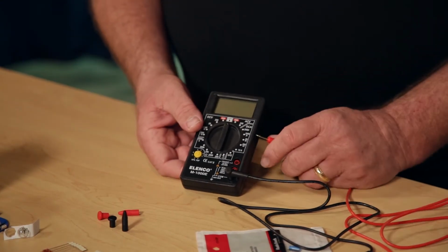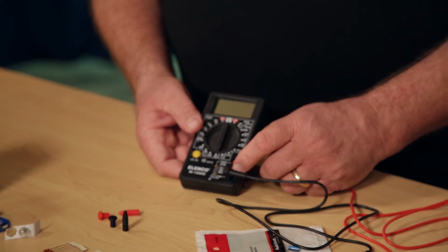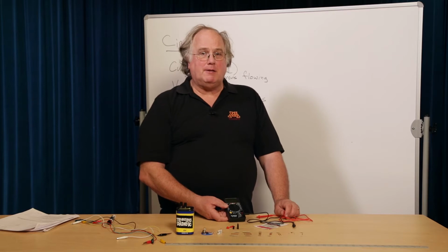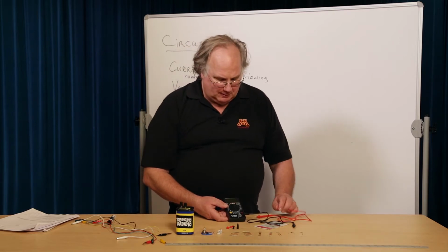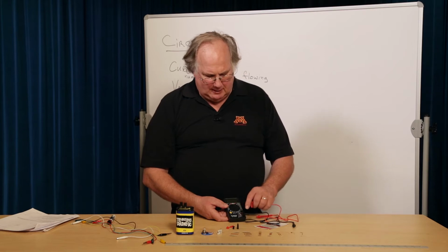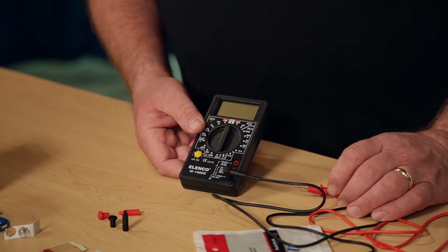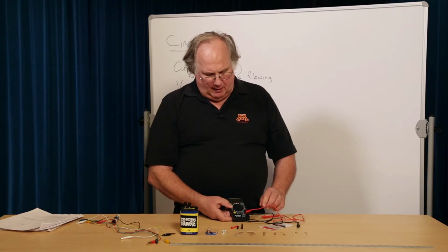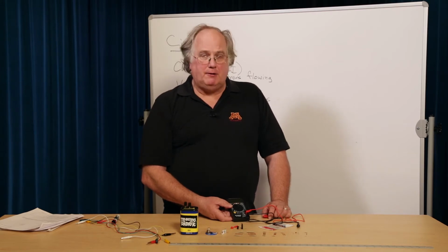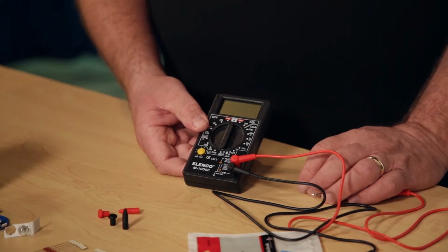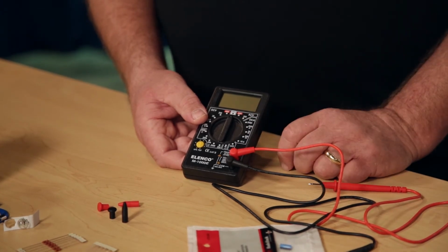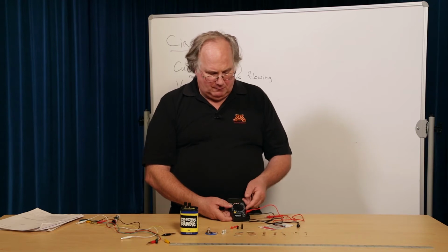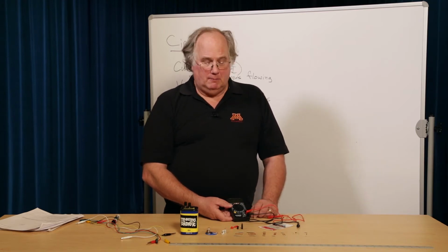But there are two places for it to go. There's a red spot here and a red spot here. What's going on is these two places are used for measuring two different things. What you measure with them is written next to the plug spot. Generally, you will use the bottom one. The one on top is used for measuring large currents. The one on top is connected to a large fuse. The one below is connected to a little fuse. And you have to be careful if you're measuring a big current to use the one on top.